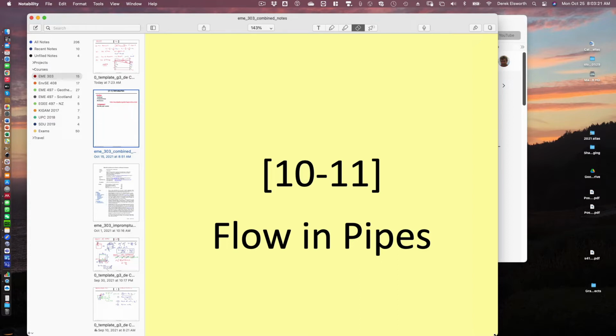So I think when we start talking about what we'll talk about in the final part of this class, last week would have been dimensional analysis. So dimensional analysis is the method that you'd use to analyze some of the experiments that we just looked at in the wind tunnel. You can figure out what the non-dimensional parameters would be that would govern behavior. When you look at the material for last week, you'll find out that there are two important parameters. One is the Reynolds number, which defines the geometry of the flow, whether it's laminar or turbulent. And the other one is the Euler number, which defines the pressures on the structure.